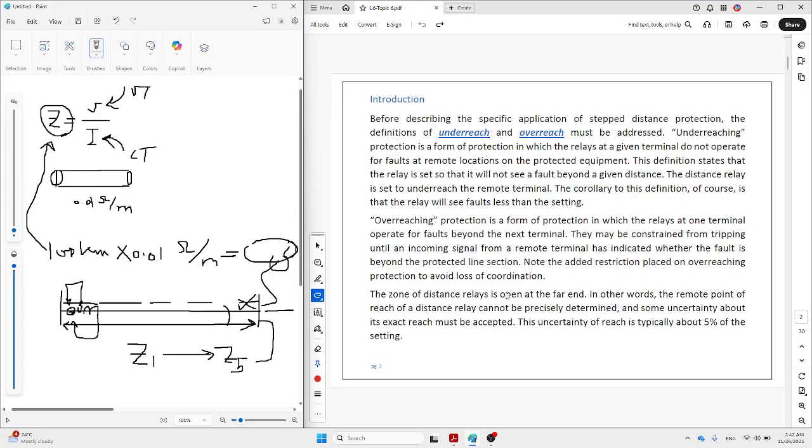Okay. This relay faced two well-known and common problems. One is underreach, the other one is overreach. Okay, I can explain underreach and overreach as simply as this. Underreach is for faults which are outside the protecting zone, but are considered inside the protecting zone. For example, zone 1 of the distance relay protects only 80 or 85% of the total transmission line, so if there is a fault here, which is at 90%, it shouldn't be inside. It means that the relay must not operate. The relay must resist against this one.